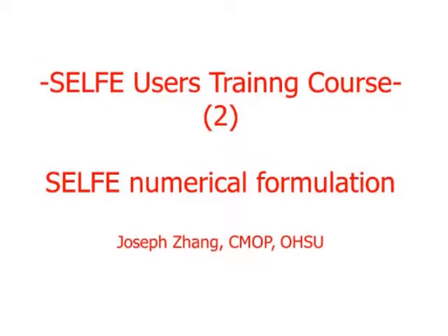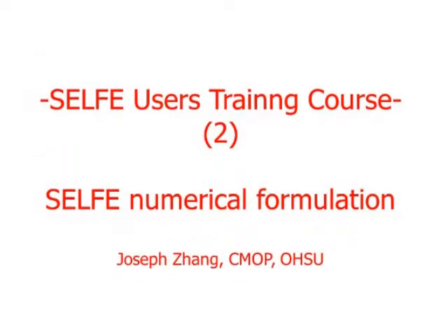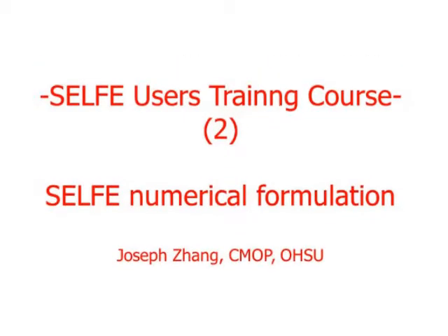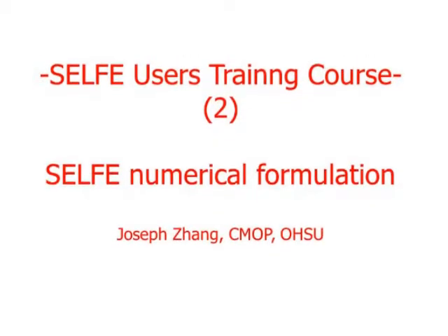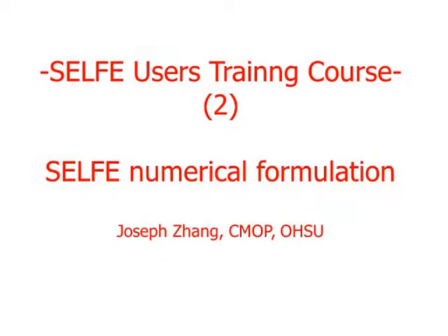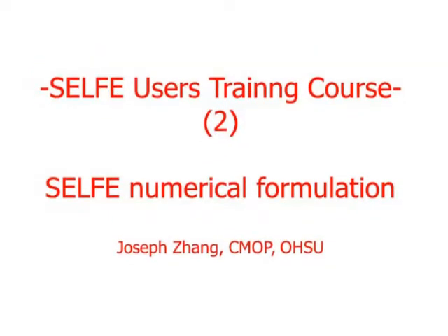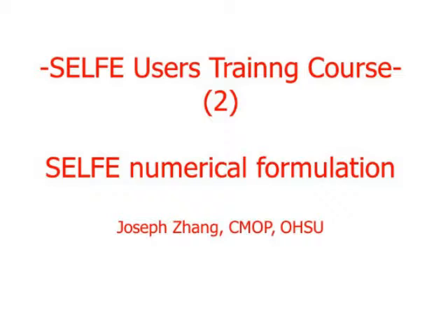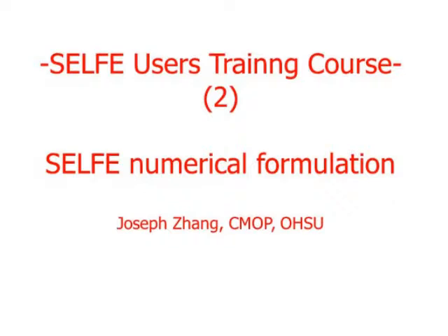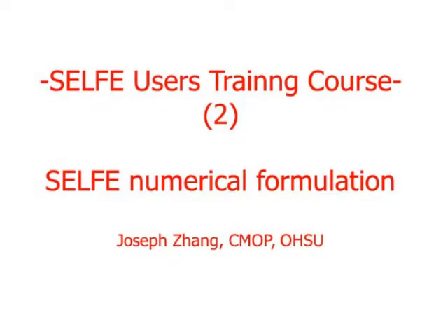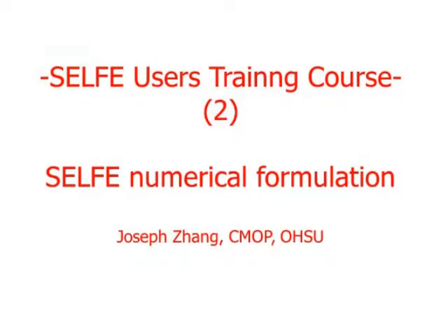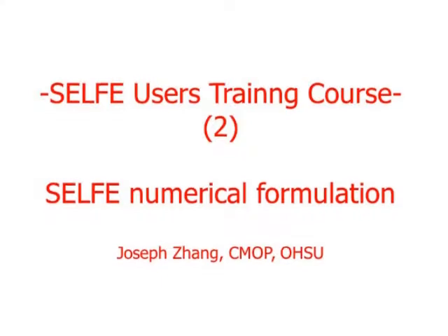So if you plug this approximation, the trial function, back into the differential operator, and if you use the Galerkin finite element method, which means that the weighting functions are the same as the shape functions, you get this integral equation with unknowns u_i. And then you need to form algebraic matrix equations for this u_i. One of the most time-consuming tasks in finite element methods is actually to assemble that global matrix, also called the mass matrix.